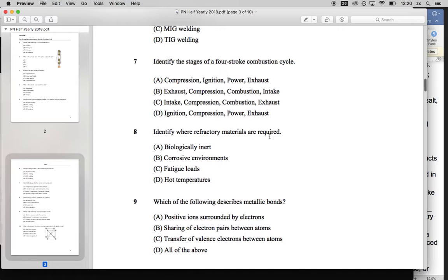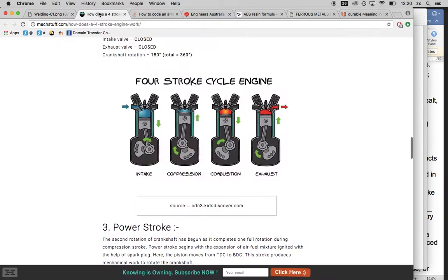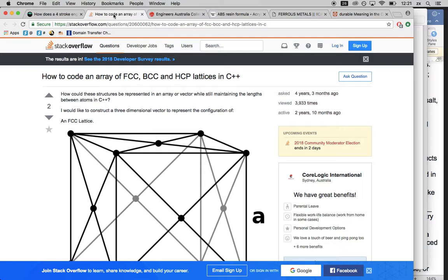Okay. The 4 stages of the combustion cycle. Again, we've talked a little bit about this. I think I gave plenty of prep to say that although this isn't explicitly in the textbook, it's not explicitly in the syllabus either, it's an important development in the history of engineering, so it's something we like to talk about. So the 4 steps are intake, compression, combustion, exhaust, which a lot of people remember as suck, squeeze, bang, blow. A question that sometimes comes up is that all the power is generated from the combustion stroke. The rest of it is sort of set up and clean up.